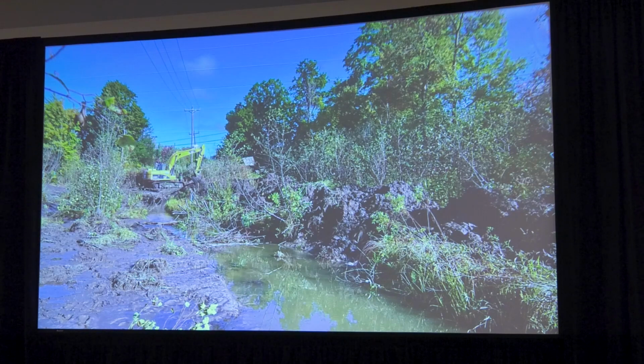And so it required some extra checking, making sure they had a really good system in place for checking elevations when we weren't there, so that they weren't getting too far ahead of themselves. This one did have some buckthorn and honeysuckle, so we had worked with the contractor to make sure they could, on their own, identify those invasive shrubs, and they were taking them off site, and replanting the dogwood and the things that we really wanted them to replant.